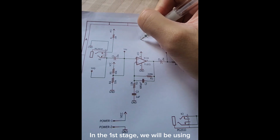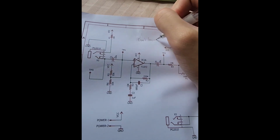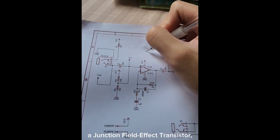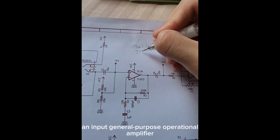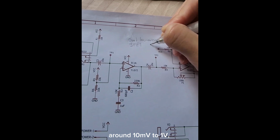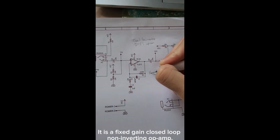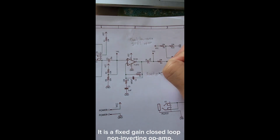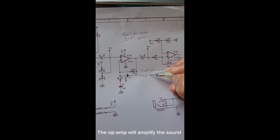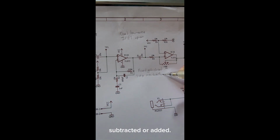In the first stage, we will be using IC1A, which is IC TL072, a dual low noise JFET, a junction field effect transistor, input general purpose operational amplifier. It produces a low supply of voltage, around 10 millivolts to 1 volt, but it does not provide any current. It is a fixed gain, closed loop, non-inverting operational amplifier. The operational amplifier will amplify the sound, causing the sound to be either subtracted or added.